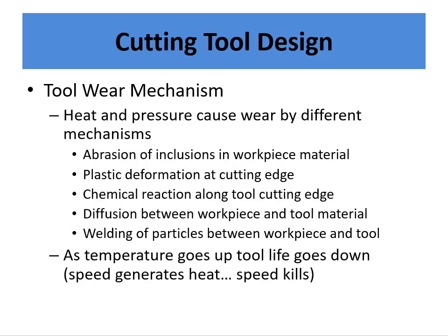So heat and pressure essentially are the things you're up against, and they both have their own ways of doing things. Plastic deformation is a combination of both, but if you have sustained pressure on the tool, you can actually deform the edge of it. The chemical reactions generally occur due to the heat, and along with the chemical reaction, that can speed up the diffusion between the workpiece and the tool material.